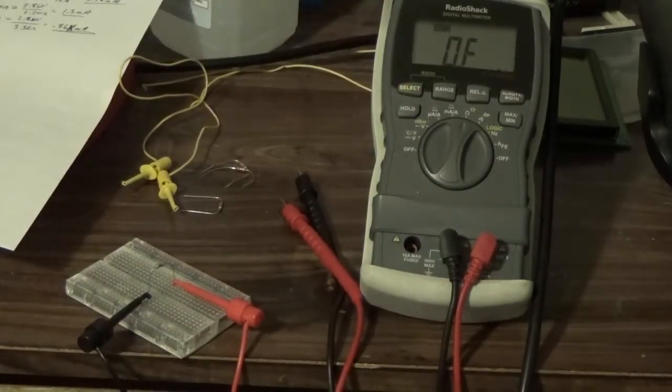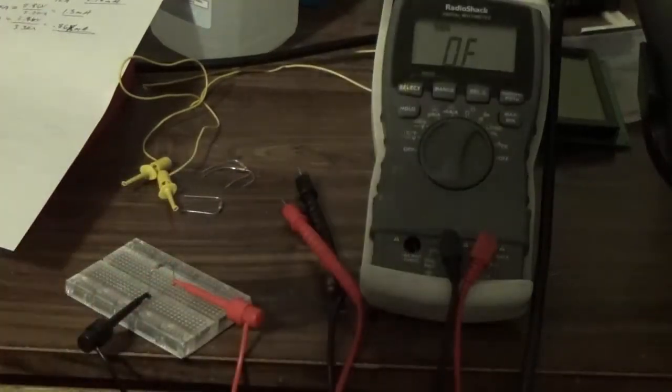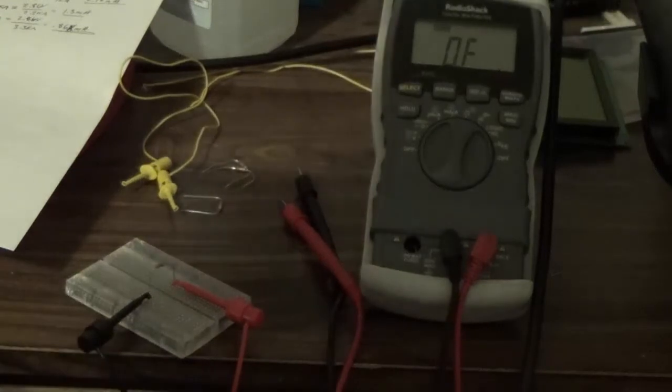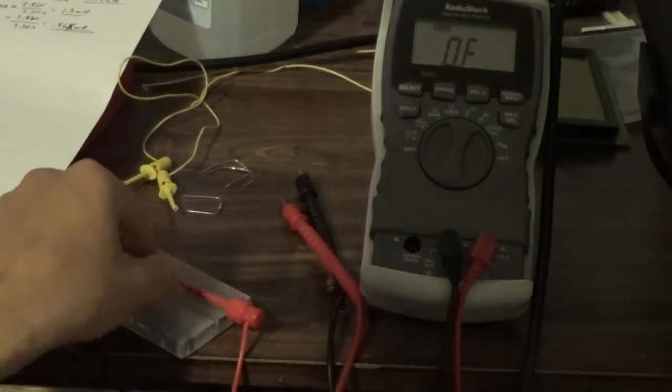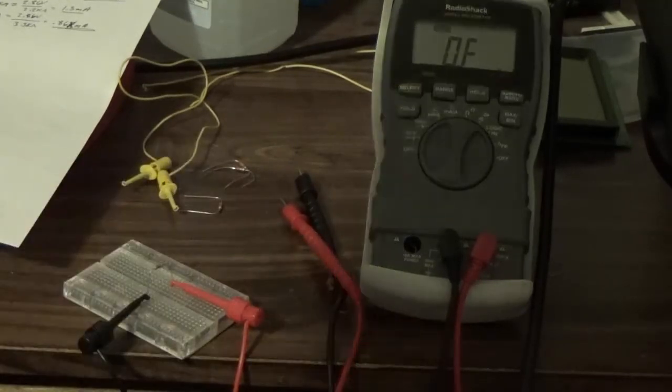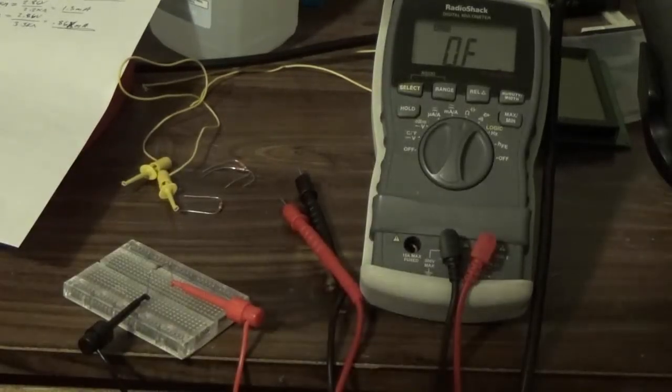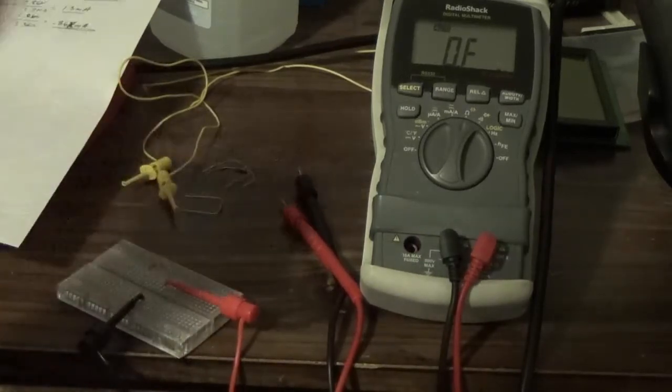And this is a stubborn guy. Right now we've got 15.5 squared, and then divide that by 300. Right now we're putting almost a watt across that thing, and it's not even budging. What a stubborn thing. But like I said, we live in a world of tolerances. So although this is a 1/4 watt resistor, it doesn't mean that it can't handle more than a 1/4 watt across it. And this thing's definitely very toasty.